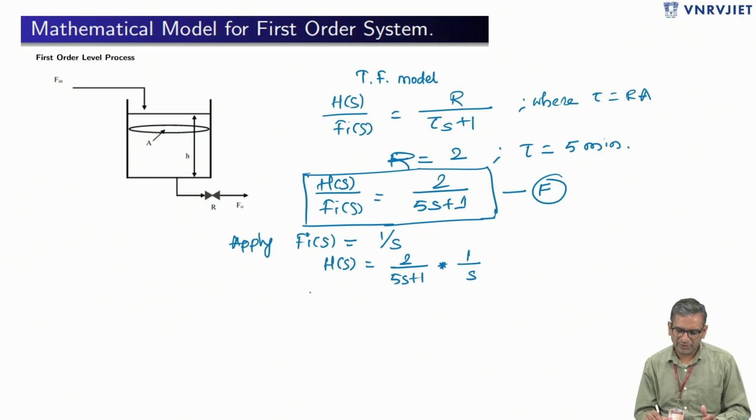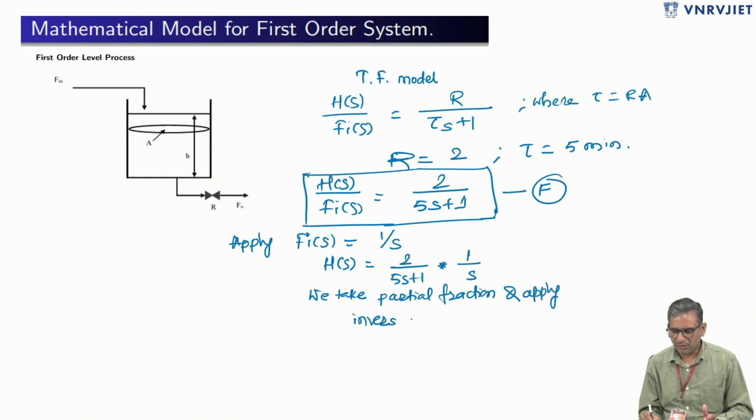So once we take say partial fraction, and later we'll apply inverse Laplace transform, as we need to know how the water level is changing with respect to time t. So we are going to apply here inverse Laplace transform.